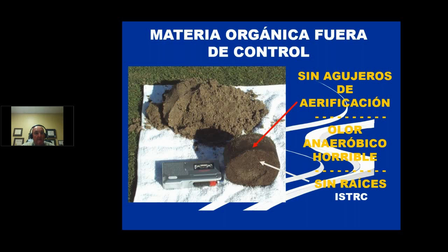Ca, calcium, S, sulfur, O4. CaSO4 is gypsum. So when it goes into the soil, the idea is I'm using my calcium to treat my sodium, so it's got to pop off the gypsum, and it also pops off the sodium. Now that sodium is in a position where the anaerobic bacteria is now using it to create hydrogen sulfide.